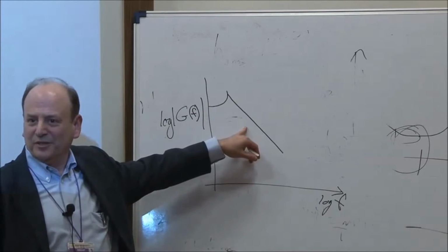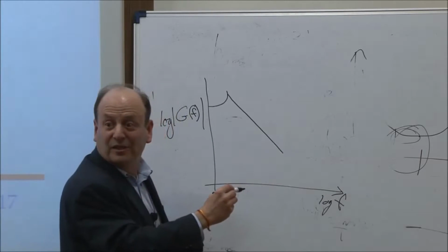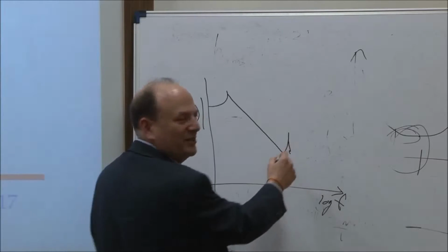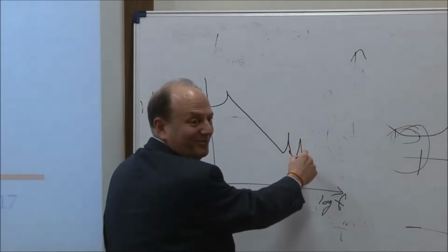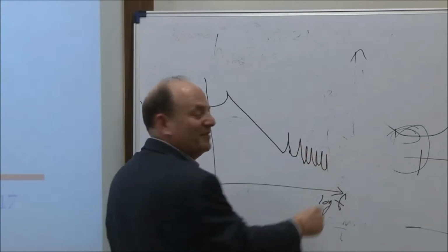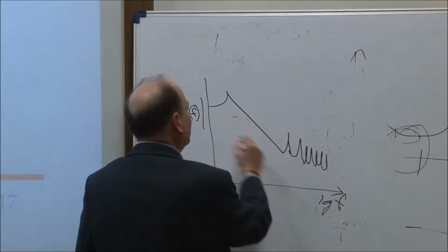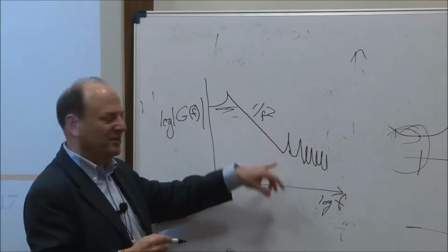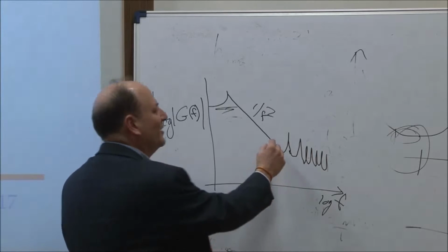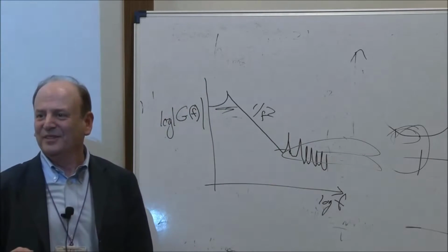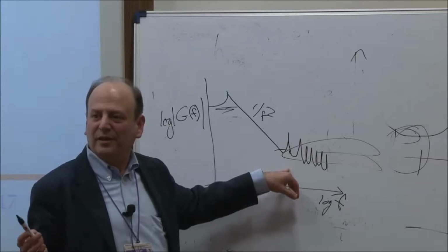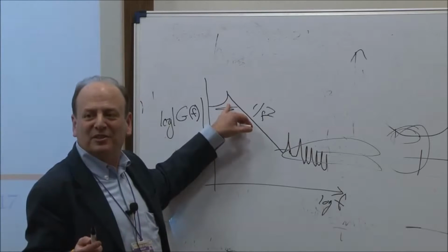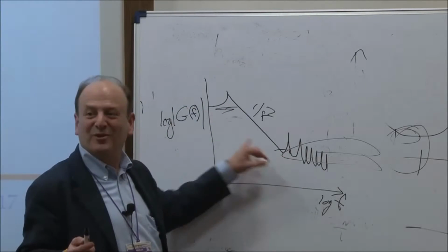Here's my 1 over frequency squared characteristic until I encounter my first normal mode. And then I'll see a bump. And then, oh, maybe it was going to recover. But you know what? There's another one. And they're crowded. And as a result, this 1 over frequency squared characteristic basically takes me from no isolation to a situation where I've got a fair amount, and then it more or less levels off. And for any particular kind of design of spring, I make this softer to move this to the left. These almost always move to the left more.